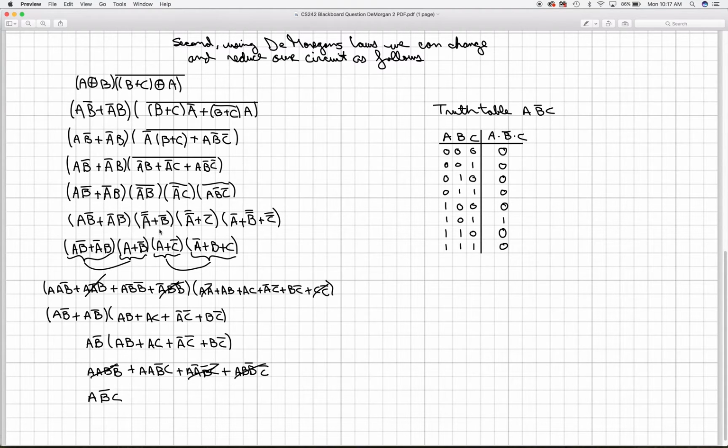All right, so now that we have this, let's rewrite everything so that we can see, for example, that the NOT NOTs are really just A. So A NOT NOT is really the same thing as A. B NOT NOT is really the same thing as B. Same thing with C NOT NOT, that's the same thing as C. All right, so what I've done is let's take care of these two parts over here and AND them together, and then we'll take these two parts of the equation and AND these two together.